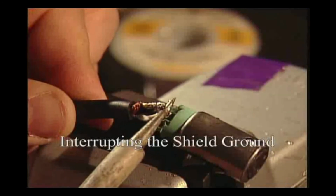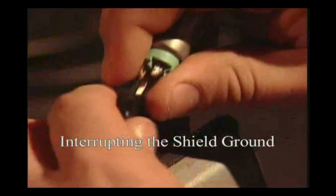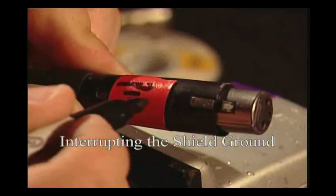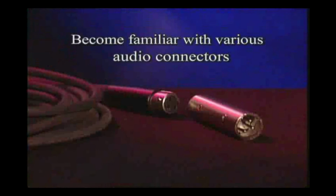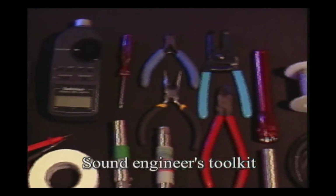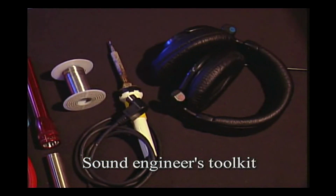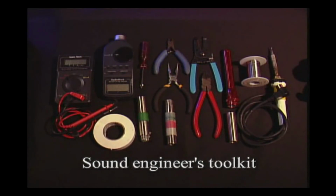The third area of consideration is safely interrupting the shield ground on a cable connector or shunt. Review the process for modifying a connector earlier in this segment. The fourth area of consideration is understanding the various audio connectors used in a sound system and being familiar with their usage. Having the right adapter at the right time can solve a problem that occurs when you least expect it. Besides a variety of connectors and adapters, a sound engineer's toolkit should include a multimeter to test wall outlets and cable continuity. A soldering kit is essential, as well as a variety of electrical tools. It's always better to be prepared.